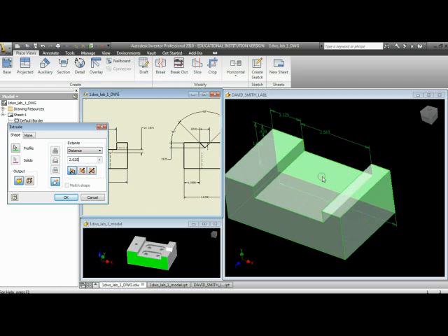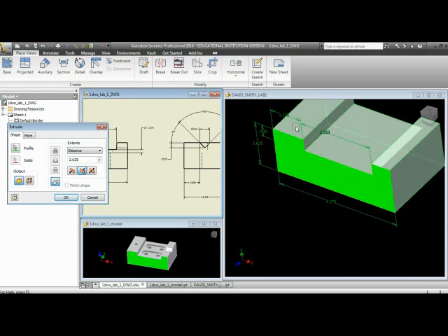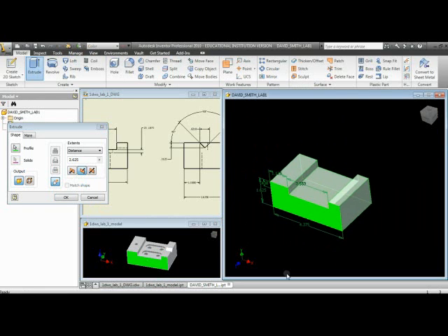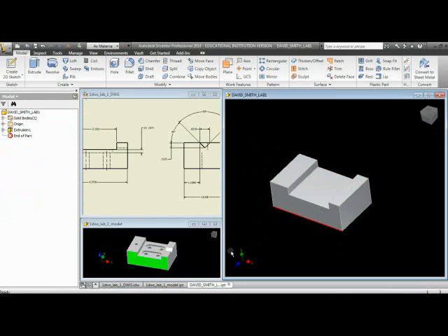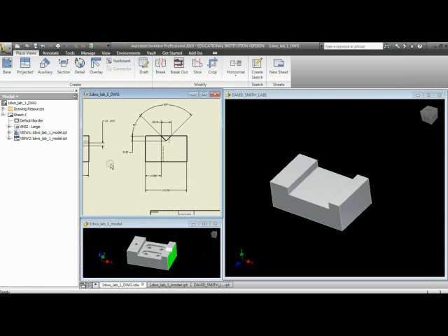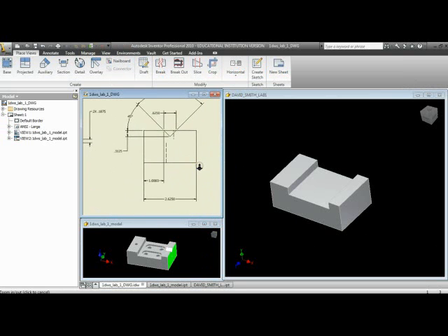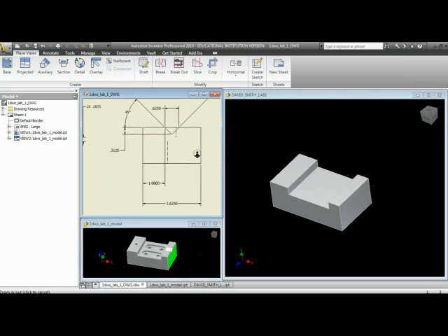Now, the first profile, you don't have to worry about picking the profile that you want to extrude. There's only one there. Later on, when we have the 3D solid, we'll be able to pick different profiles, so we'll have to be more specific. We also can't do any of these Boolean operations. We can't do a join, a cut, or an intersect, because there's nothing to cut or intersect with. So for that reason, those are all grayed out. Another thing we need to note is the output. It is a solid right now, or it could be a surface. We want to stick with solids for now.